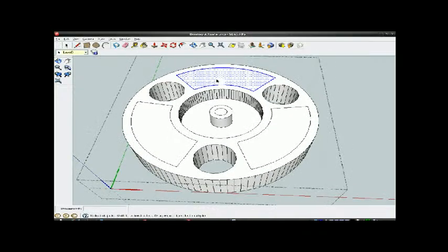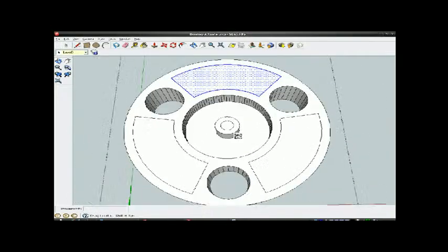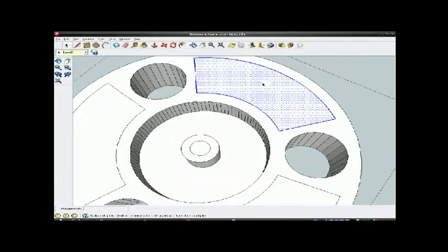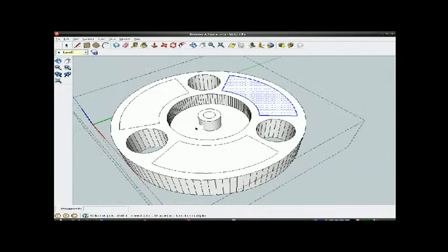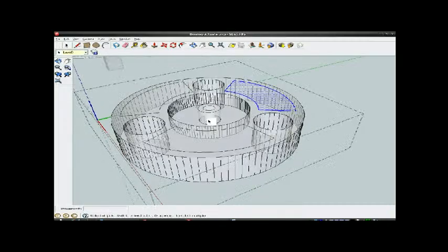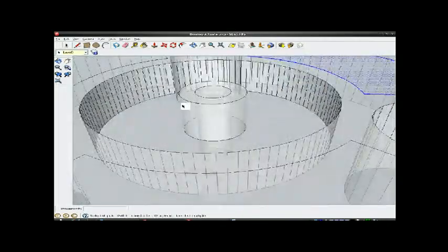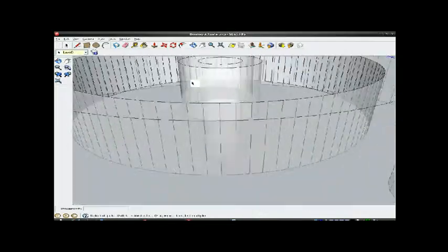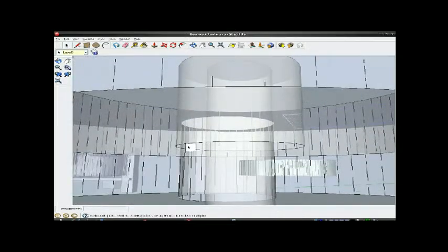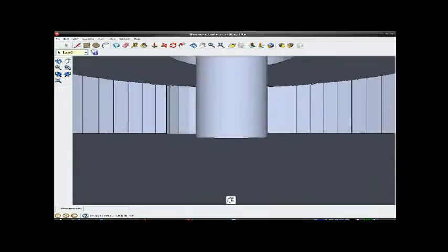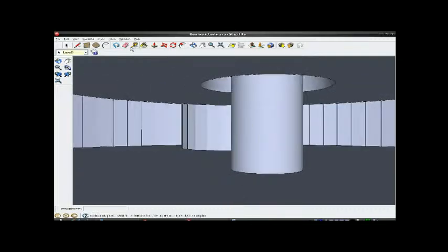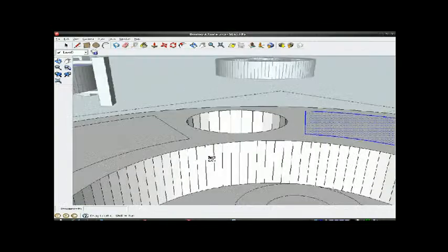It should be exactly spaced right because I use the same degrees and everything. So now all I have to do is get rid of all that extra plastic and save myself a ton of money as well. So I need to take that down to, let's see, how thick is that? I forgot now. I'm going to go back to X-ray again. How thick is that thing in the middle? Because it could be a bit thinner. I need to be inside. Right. Turn X-ray back up again. How far is that? That is 10 millimeters deep. Oh right, I can take a bit out of there.